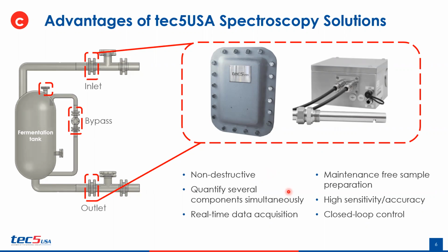It also quantifies several components simultaneously. If you're looking in a wide spectral range, in the near IR range for instance, you have a few different key regions that are associated with various components, and pinpointing those different regions can allow you to quantify multiple components with a single measurement.